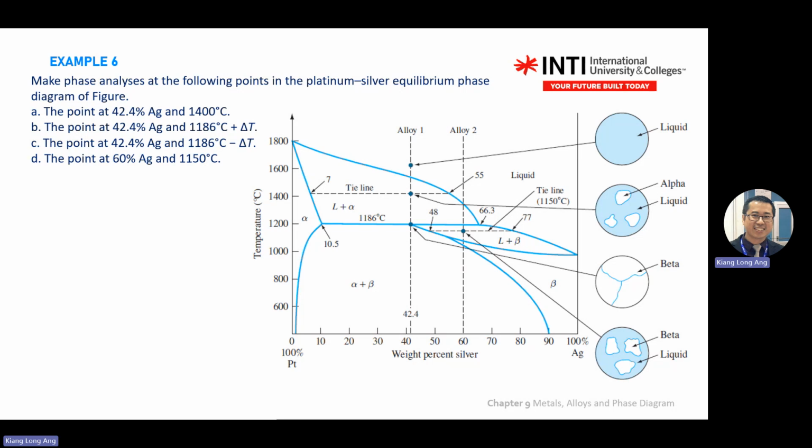So typically, when you drop temperature from a very high side of your y-axis, in this case, if you drop your temperature from 2000 degrees C, you will start with liquid. Then you'll see it start to cool down. When it starts to cool down, it starts to have small particles, like chicken pox. Then it will grow, become crystal, then it will grow until solid.